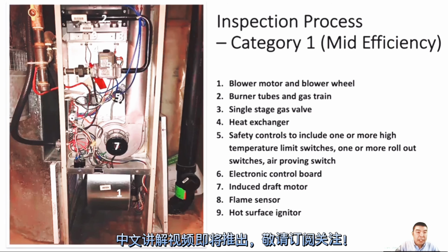If you see a hot surface igniter, you should check it. Normally it is a silicone material. When it has been running a long time, you can see some white stuff on the outside of the igniter, so it may be burned.